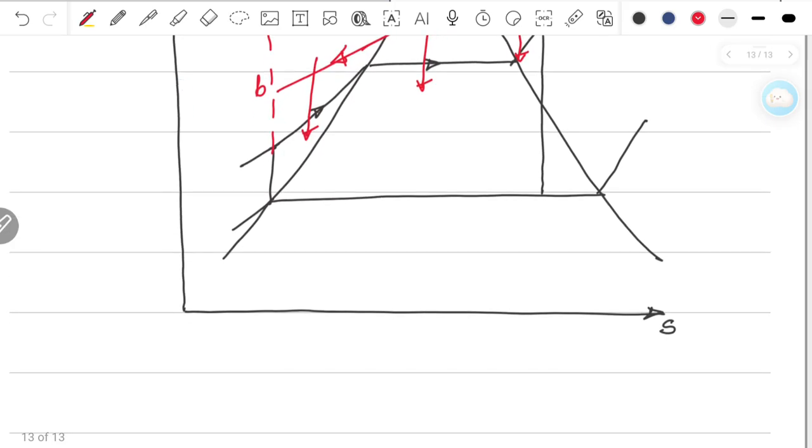What about the condenser side? Here also, the steam is getting condensed. That means steam is losing its energy so that it can get converted into saturated liquid. Similarly, to gain this energy, water must be circulating around the condenser, so that water is gaining heat. So here also you can see there is a temperature difference, and this temperature difference is again resulting in external irreversibility.